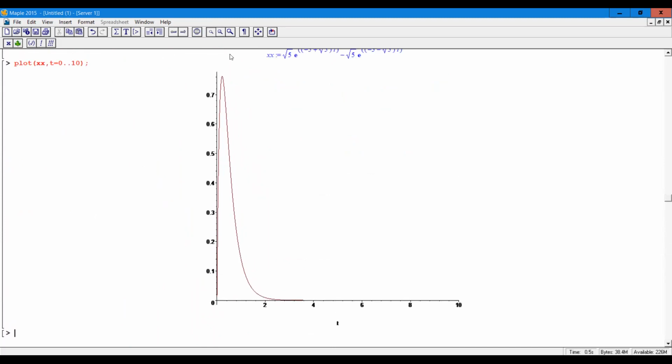Due to the initial condition, which is 10 meters per second, it will go to about 0.8, and then will come back and will stop at x equal to 0. So this is the total response, and after about 2 seconds, or about here, at t equal to 3 seconds, the car will be completely stopped.